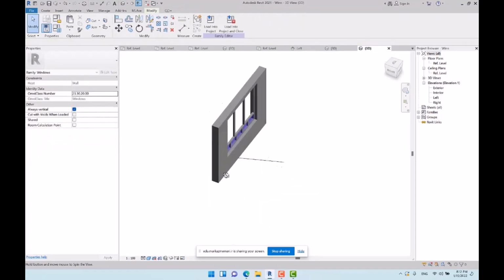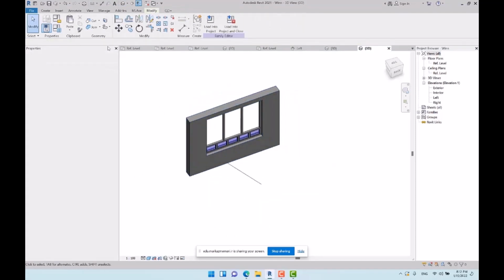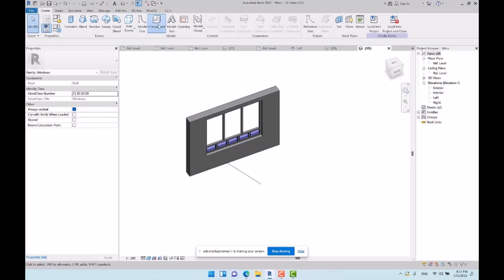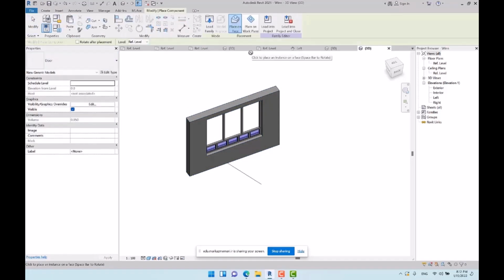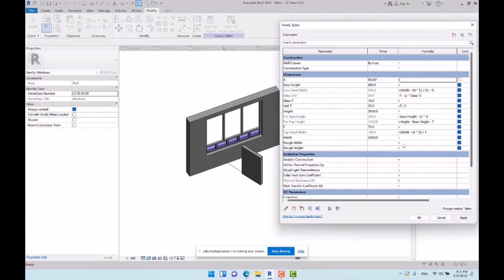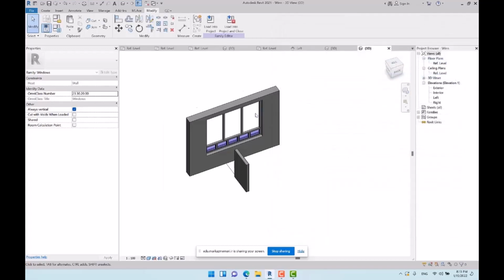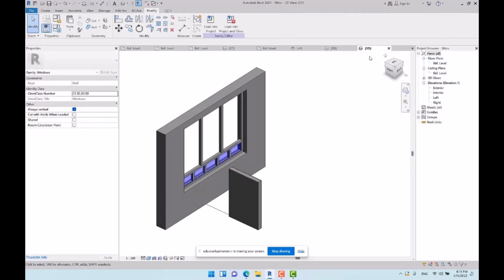I open 3D view. Check this out. I pick component. We got the door. And I choose place on work plane or work plane base. Then I place it on the reference line. Let me test the angle, 90 degrees or 0. Even 0 is accepted here, since in some of the approaches, specifying 0 degree is not accepted, but till now we have done correctly.